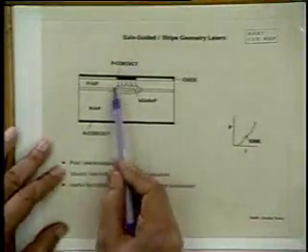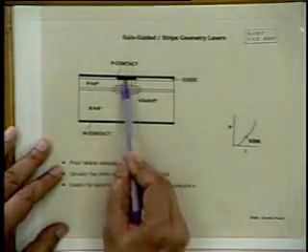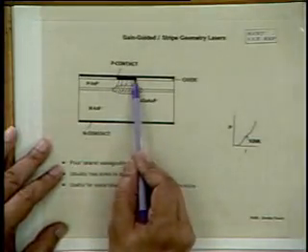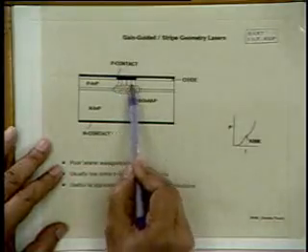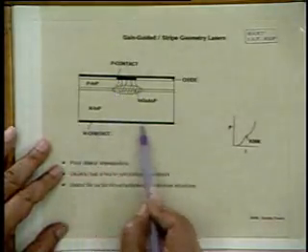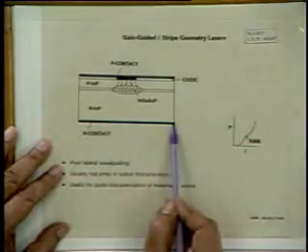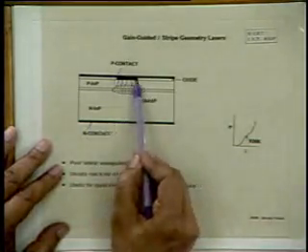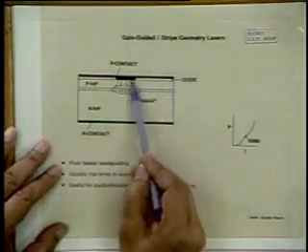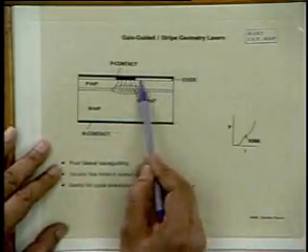Okay, and a typical stripe geometry laser is something like this. Okay, here's the stripe. Here's the active region where the light comes out. This is a total bottom contact, N-type, as a metal. Here you have a limited area. And how do you define this? Well, you can have an oxide stripe.